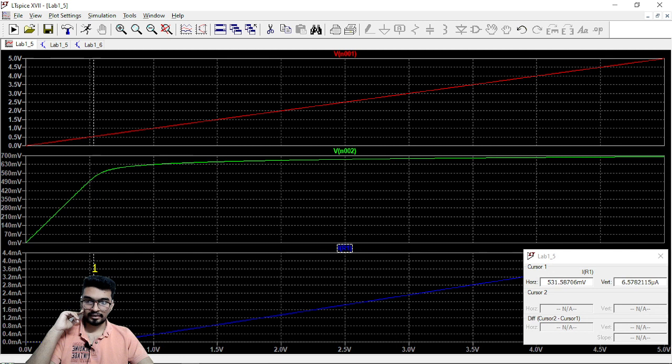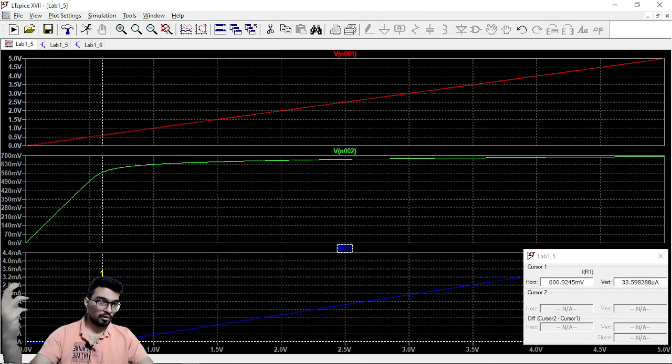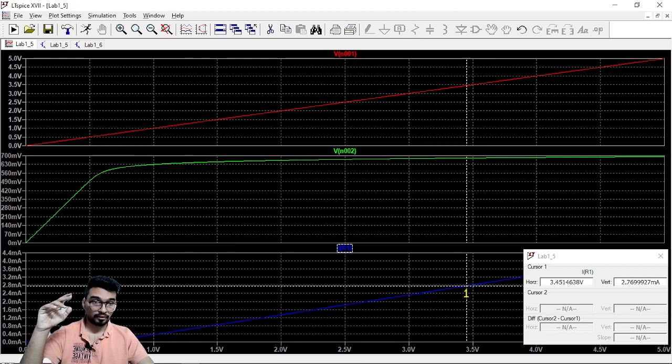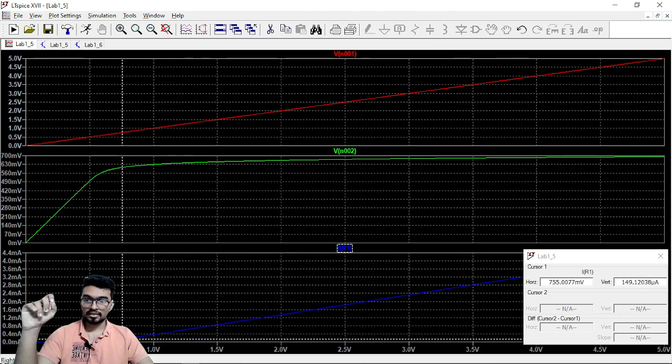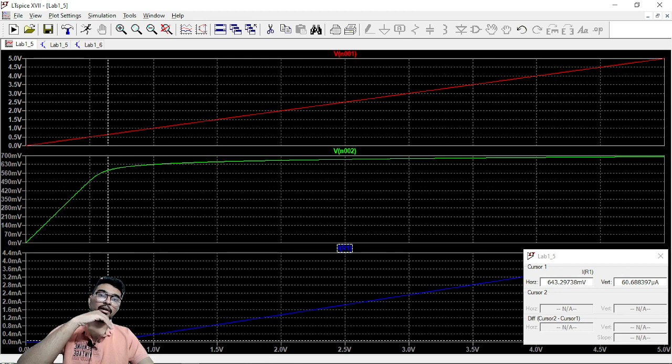Okay, so approximately it is 0.5 volts. In this range, 0.5, 0.6 here, you can see that this current is picking up, this graph here, from the pico, nano, and micro range, and it is going to these particular values. The input voltage here is varying approximately; you can say that 0.5, 0.6 volts approximately are the voltages where this current is flowing.